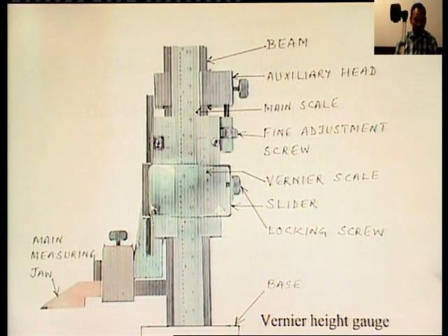It is attached to the beam above the vernier head. It consists of suitable fittings to give a fine adjustment of the slider and clamping screw. It is also provided so that the slider could be clamped to the beam effectively after the fine adjustments.